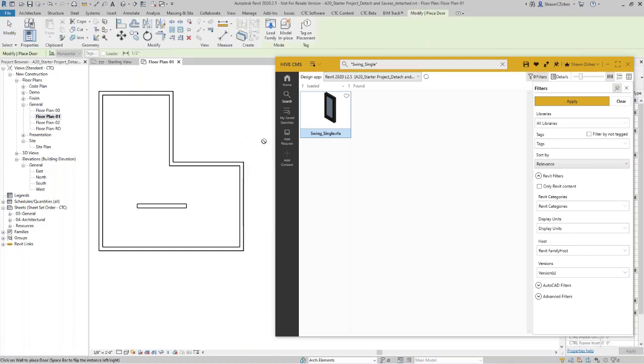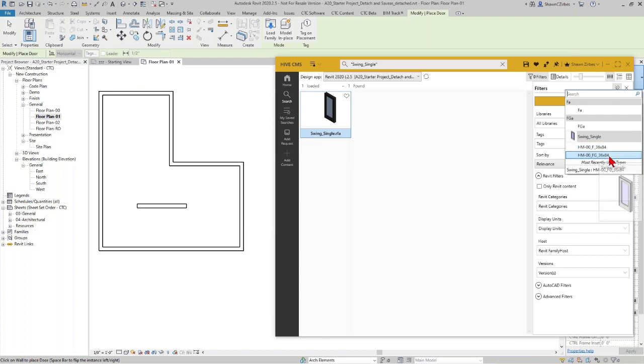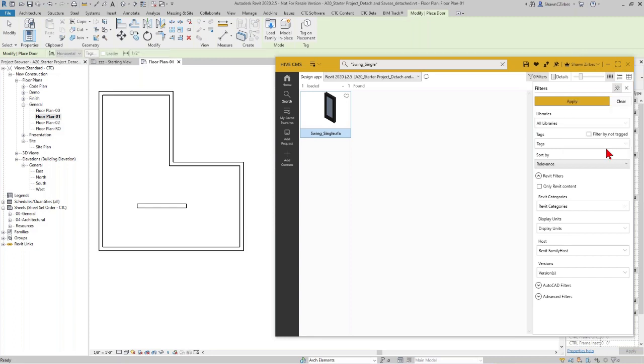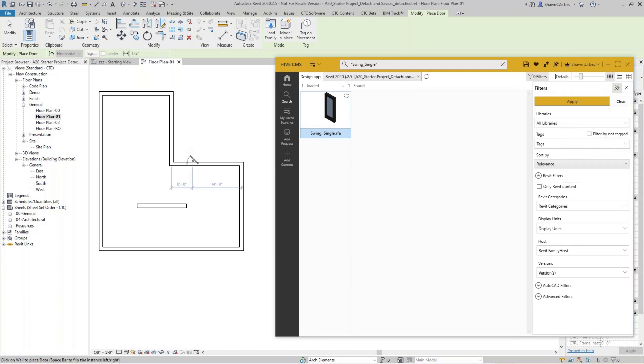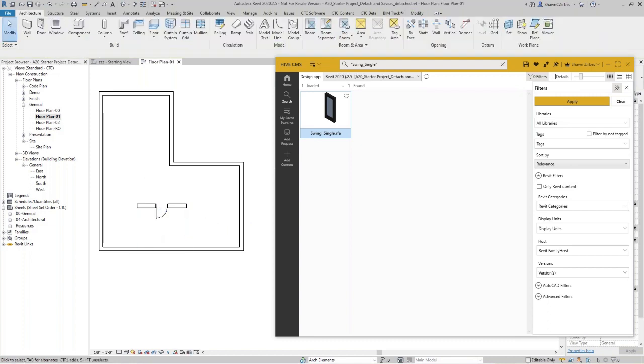And then it's going to initiate the placement of one of those 2 types, whichever one I happen to have chosen last in that dialog. Okay, so if I wanted to insert just the basic flush panel door, 36-inch by 84-inch, I can do that, drop that into my model. That door now exists. We're all happy.